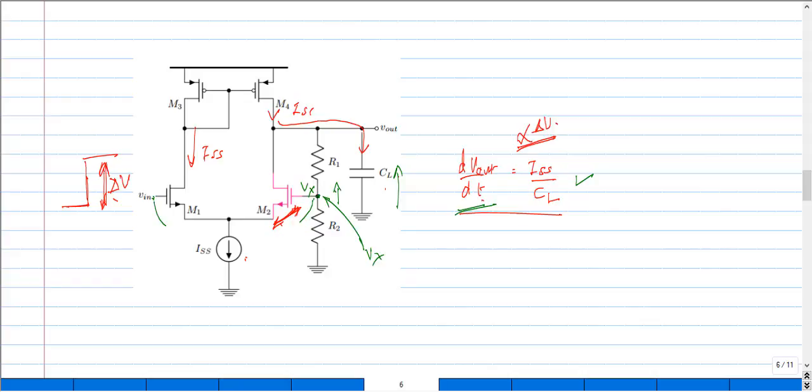So when the potential difference is so small, because this node keeps on rising, it makes the difference between this Vin or the M1 gate and the M2 gate very small, such that the transistor M2 will get into the saturation region, which is basically turned on.